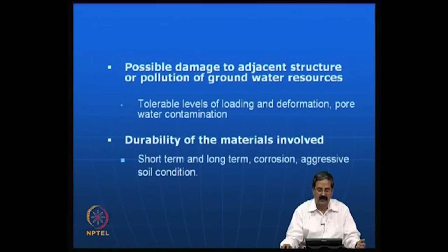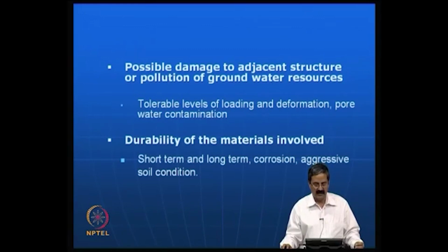Then when you are trying to use a ground improvement technique, you should also understand that, for example, you have an apartment, and next to that you want to construct another apartment. If you start excavation next to the apartment, what happens? That owner will come and sue you, because the moment you start excavation, there will be some cracks in buildings and there will be a problem. So, one should understand what are the tolerable levels of loading and deformation. For example, you know about the concept of differential settlements and total settlements, right.